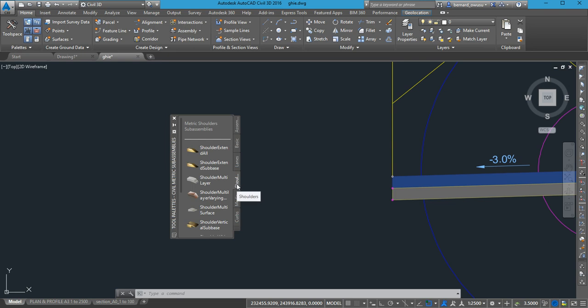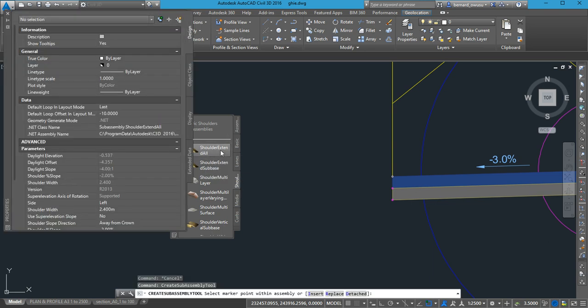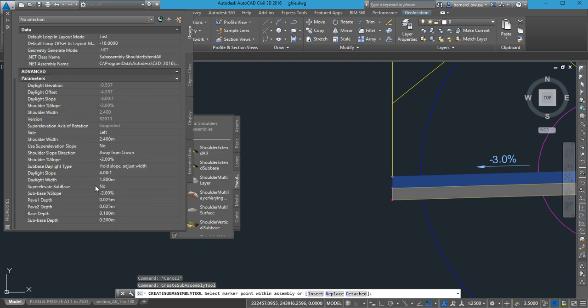Amma, you had a problem? Okay. So after lanes, we go to shoulders. Have you selected shoulders? So you decide on which shoulder you want to use. Let's use the first one. Shoulder extend all. So select that one, shoulder extend all. Have you selected? Yes. Now I'm sure we are familiar with this. Now we understand the language. So edit the information. You can watch what I'm doing.